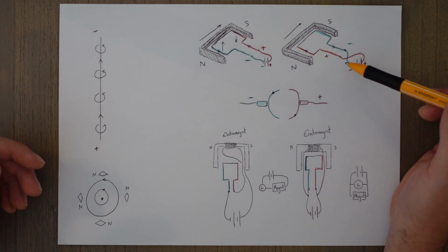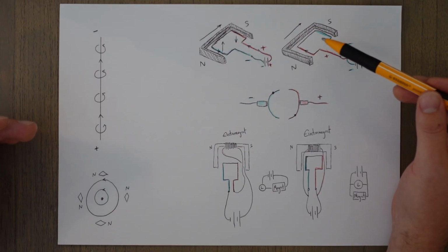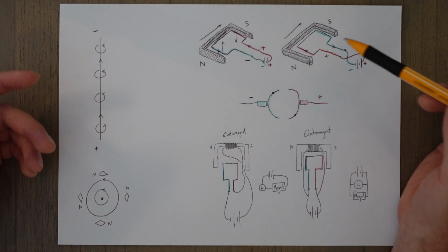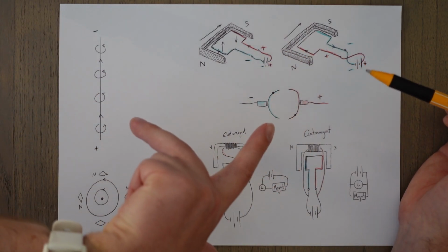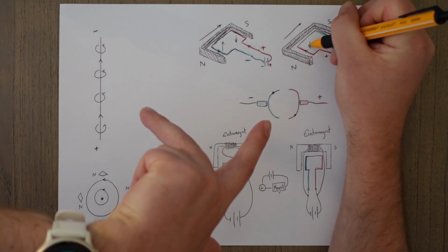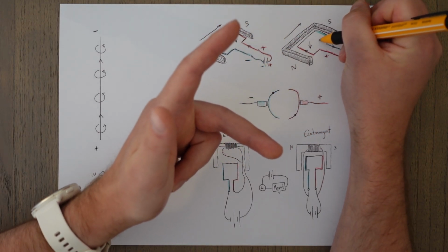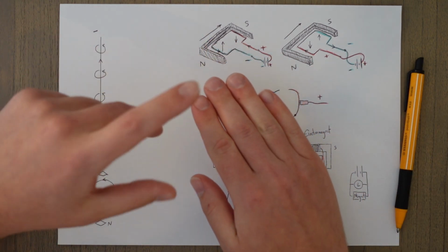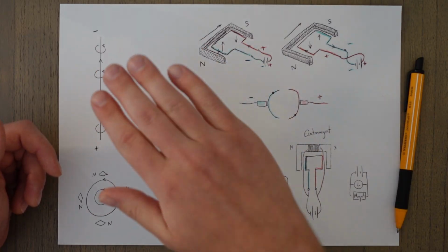But if we attach this side of the loop of wire to the positive side of a battery, and this one to the negative side of the battery, then everything starts off fine. But as we reach a half rotation, our hard connection to the positive side means that the current is now flowing this way, so it would cause a downward motion. And in the blue, our current flows this way, which would cause an upward motion. So we get into this situation where we've got the motion changing direction. You'd get a motor that just does this all day, which is not what we want.